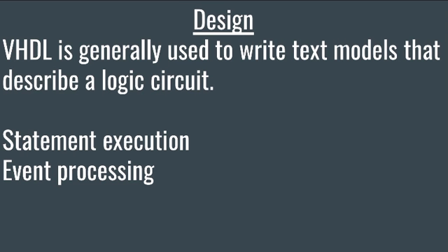In VHDL the simulator is typically an event-driven simulator. That means each transaction is added to an event queue for a specific scheduled time. For example, if a signal assignment should occur after 1 nanosecond, then the event is added to the queue for infinitely small time step, which means the simulation alternates between two modules.